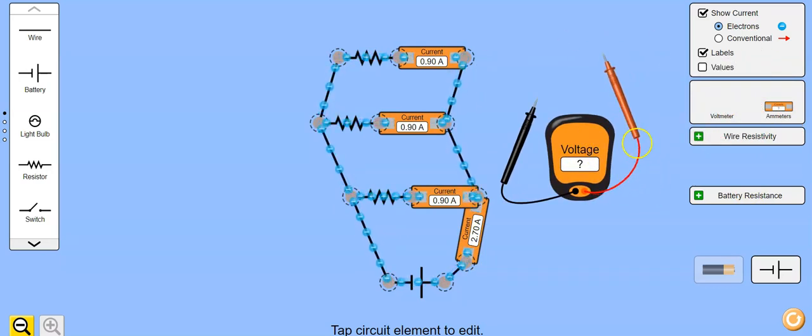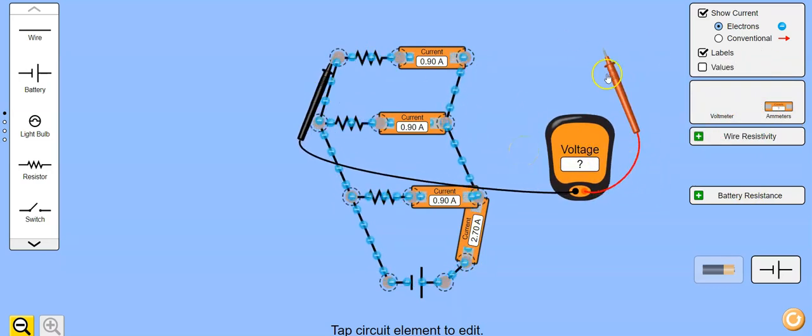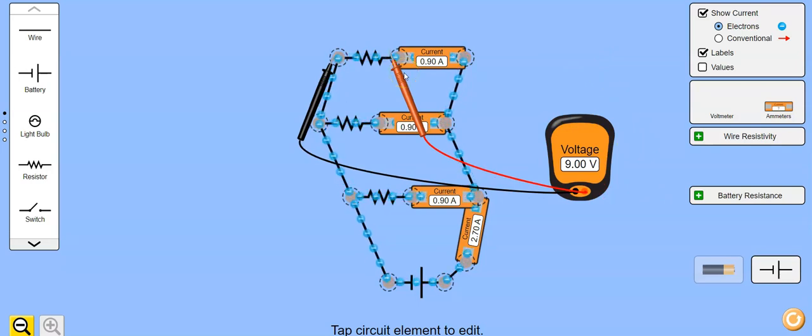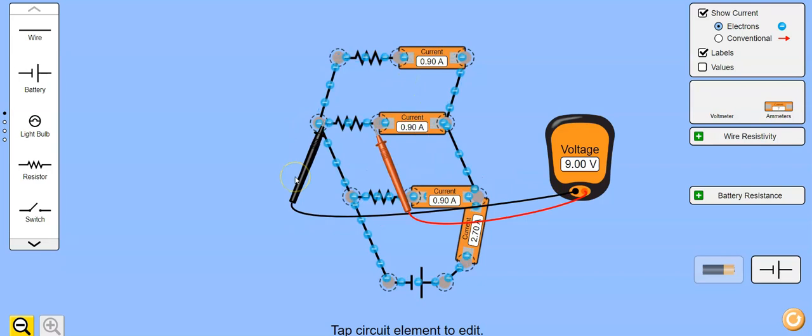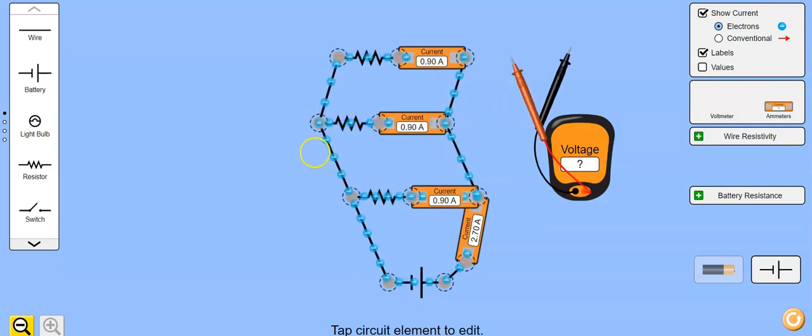Now for voltage, you're going to do the same kind of reading, going across like this. So you'll see what the voltage is across each resistor. Okay. You'll notice in the lab, it actually asks you to look for both things for this. So that's basically how you do things in series and things in parallel. So this one's parallel. Series would be just one straight line. Pure parallel is multiple lines like that. All right. Good luck. Hope you have fun playing with circuits.